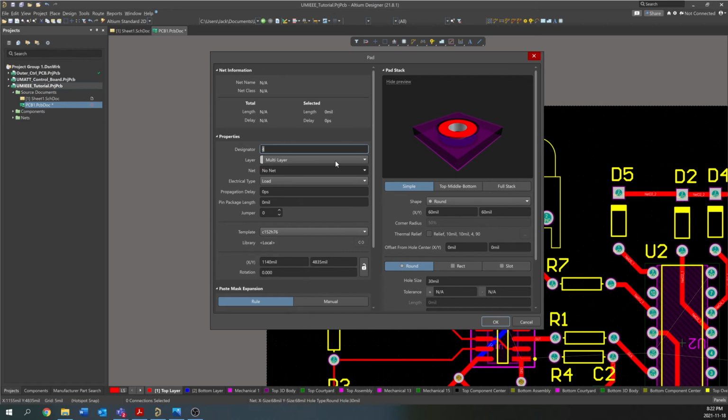and we can go here and change the net of the pad, and we're going to set this net to ground. Usually your through holes are set to ground. So it's one way to give a ground signal to your board, or to bring it to equipotential with everything else. We're going to change the hole size itself to, let's say, 150 mils for a larger screw. Now you can see that everything went away here.